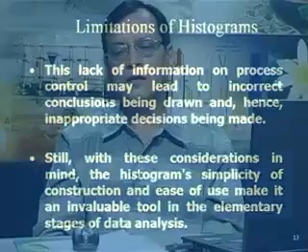So, although it has limitations, the histogram is a very simple tool. Once we have collected the data and do not know any analysis, the very first step is to develop the histogram. Once the data is converted into the histogram, it gives you some information about the process: how the process is centered, whether it is behaving normally or not, and what is the extent of variability or deviation of the data from the mean value. That information we can get from the histogram.